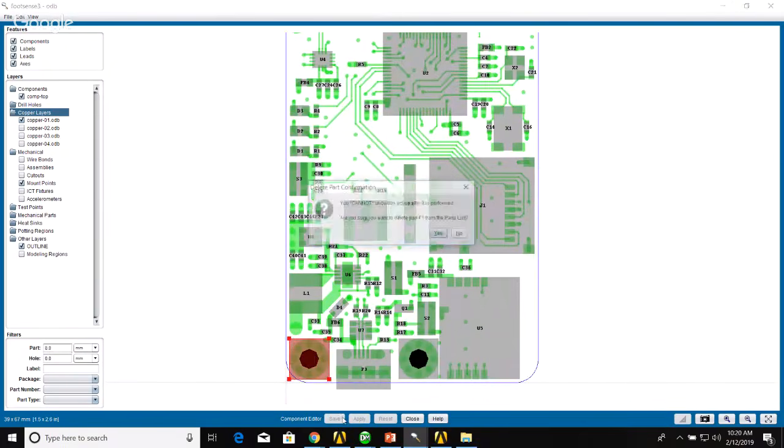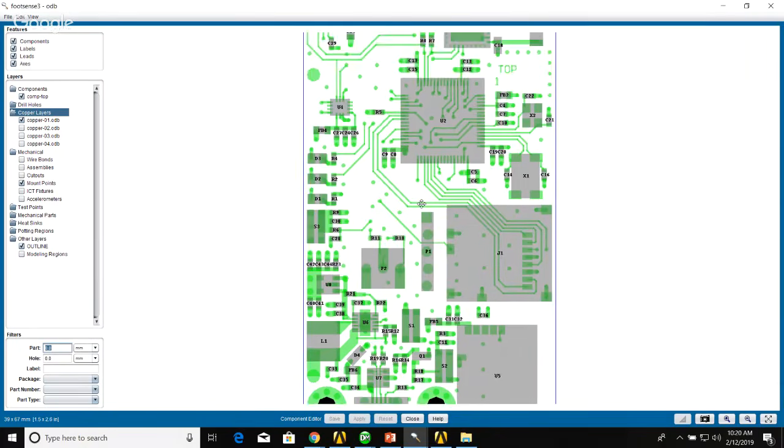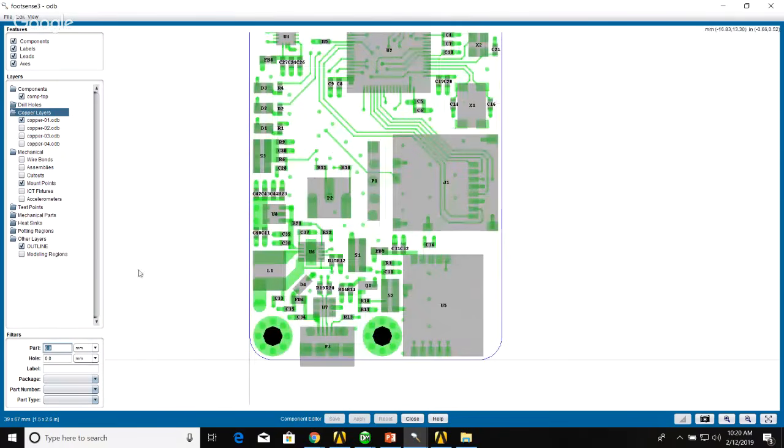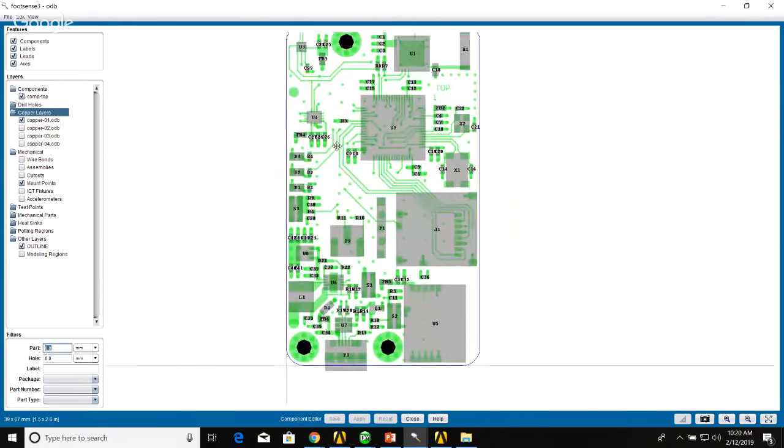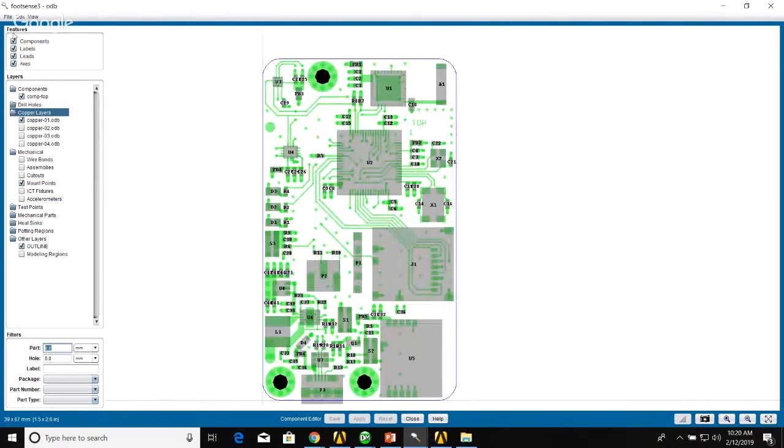So Sherlock is a tool that allows you to modify the model and get it prepared for analysis. It then builds a clean geometry for you, so you don't have to worry about defeaturing it. Once the model is created here, everything will basically be blocks. If you have fancy components you want to put in, I'll show you how to do that afterwards. But now we have a model that's cleaned up and pretty much ready to go.